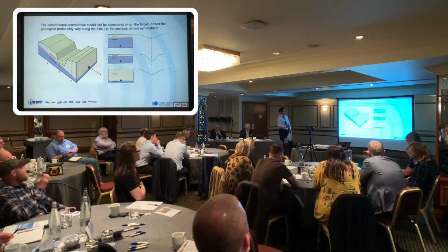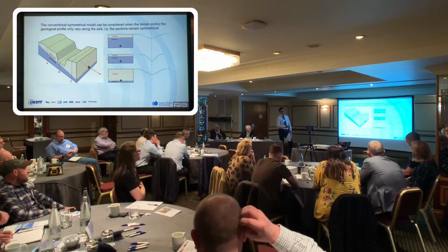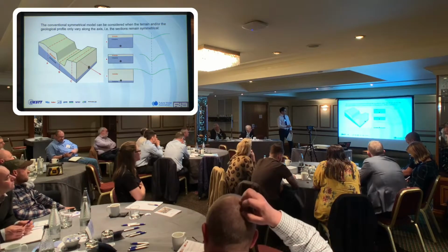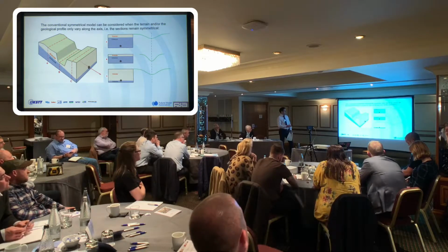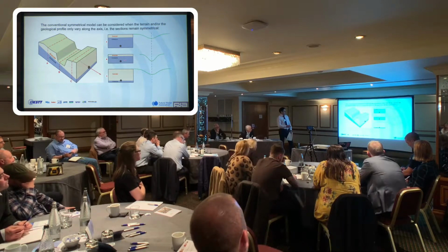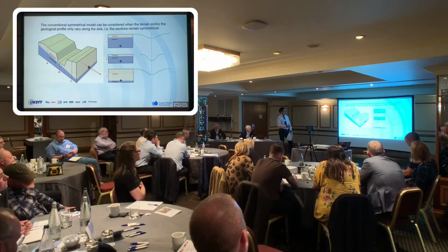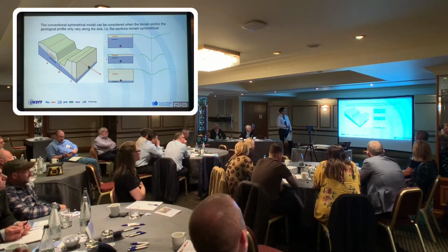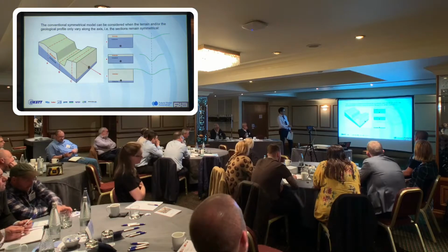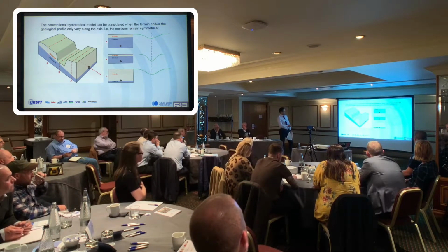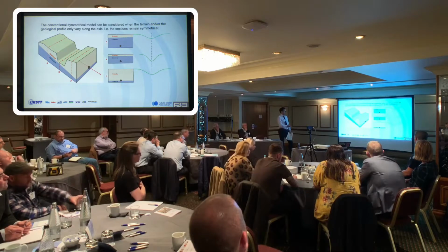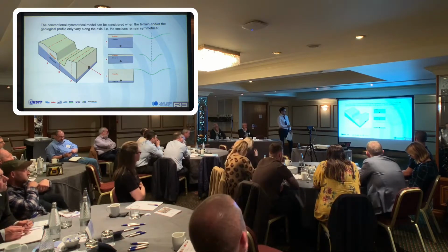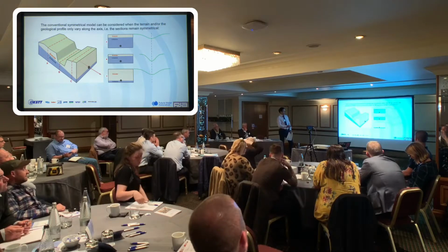When you model, if your drive is going through a varied topography, you've got to split it into slices. So you can see here, you've got a slice there, and as the cover is reduced this way, you're going to get a slight increase in settlement there, and as it gets deeper, it reduces again. Often, with a limited-length drive, the topography is roughly the same across, so it's not necessary to go into too much detail and consider too many options.